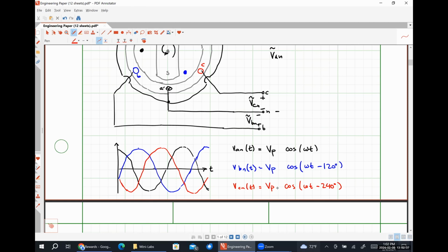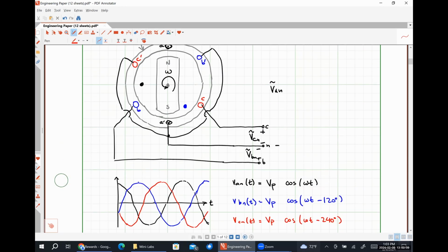That being said, on the load side of things, you'll see 3-phase loads with 2 poles like we have here, but you'll also see 3-phase loads with 4 poles or 6 poles or 8 poles or whatever. So it's looking like a 6-phase system, a 9-phase system, a 12-phase system, etc. All that translates to is that the rotor spins slower because it doesn't have to make a full revolution before it hits the next peak value.